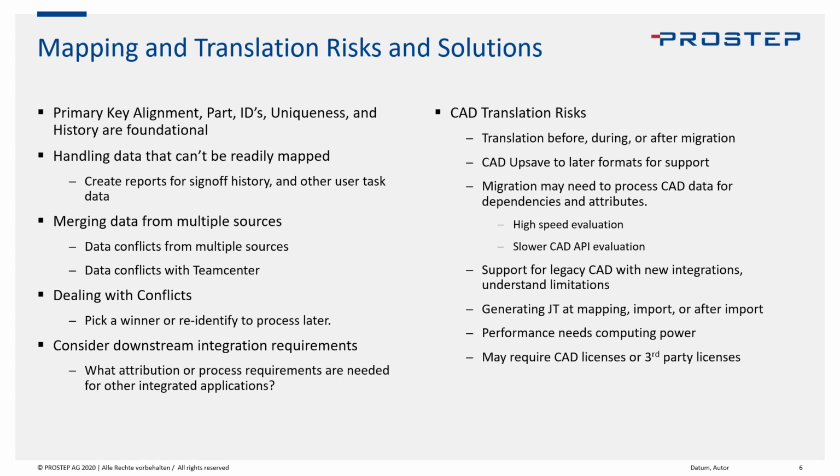So CAD integrations don't always support all those legacy CAD files that you have. So you have to have a mechanism in order to load it into a preferred format that you can then use, and that might be upsaving your SolidWorks data, upsaving your Creo data, something like that, to a later format that's then supported within the application.